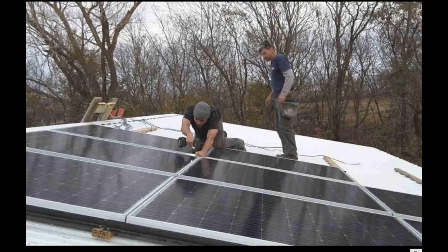Okay, next is the photovoltaics, the whole electricity system. We are getting that automated, but you can say more in the route of monitoring. Right now, because of our low nighttime energy operation, we want to understand exactly what all the loads that we're using are. So we're currently installing, with a collaborator from Michigan Tech, Joshua Pierce's group, an open source power meter that tracks every single power device in the house, and it logs it. So we're logging current and voltage, meaning the power, for every single load in the house.